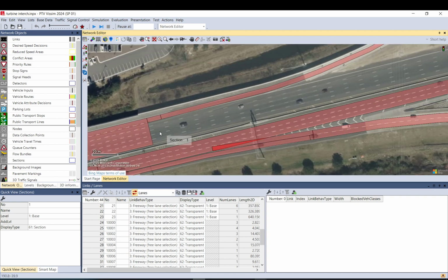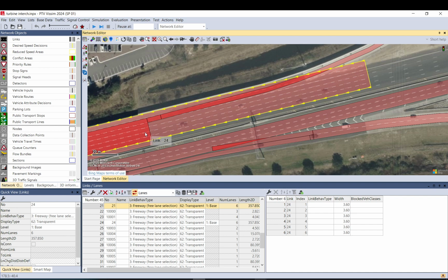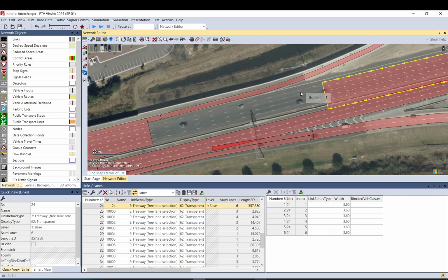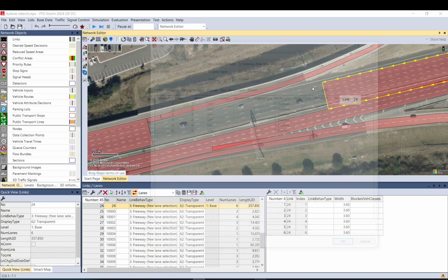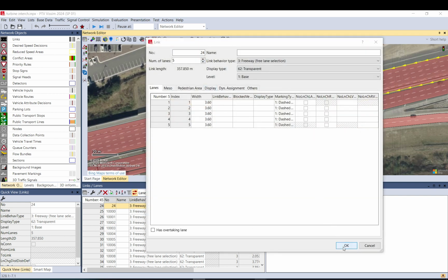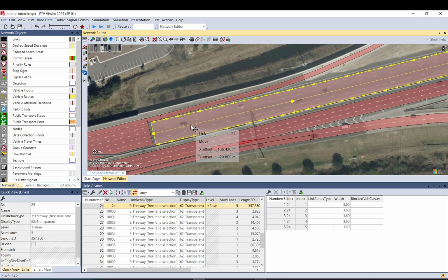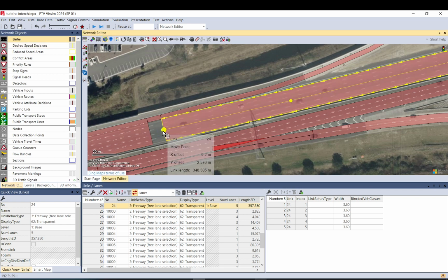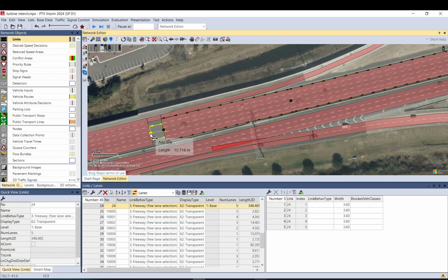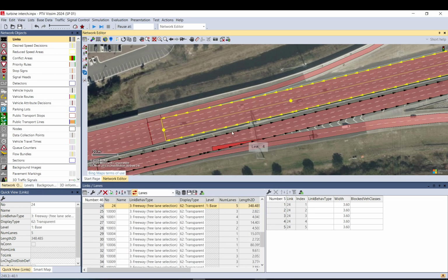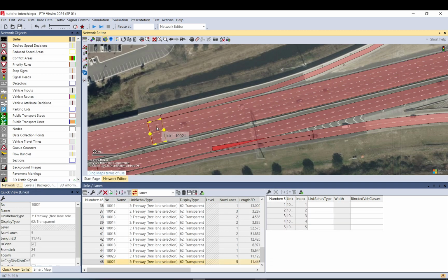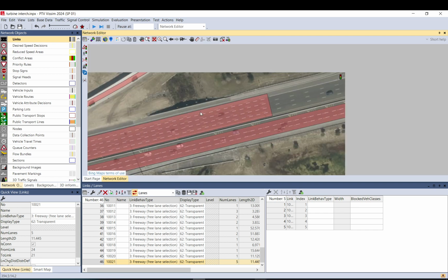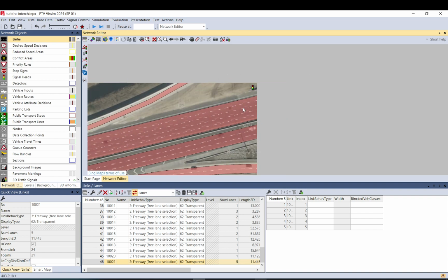Then we need to do this one here. So how many lanes do we have? It's 5. And for such connectors, I don't need to change the lane changing distance because it has no impact on it, since all of the lanes connect the connector.